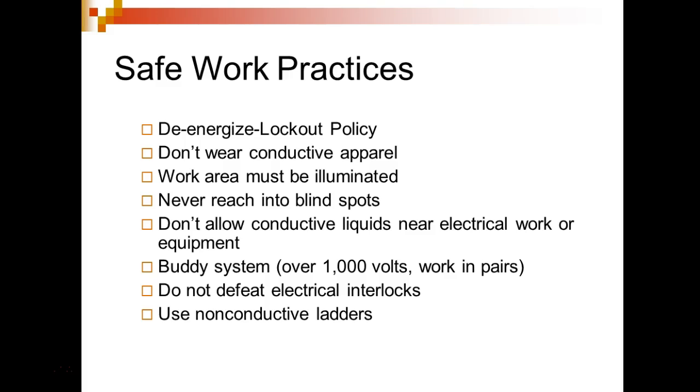It's called lockout and tagout for a reason, because legally I cannot remove your lock. Now we're going to do that. For one thing, locks cannot be combination. They've got to be keyed locks, with one key only.